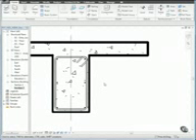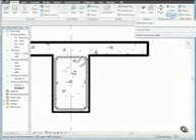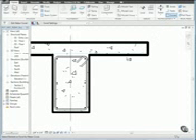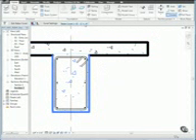Next, we'll select a default setting based on the size of the rebar that was placed in the beam. In this example, the rebar size is number 4. From the Reinforcement panel, click Cover and select the beam. Then, on the Options bar, for Cover Settings, select Interior, Shells.